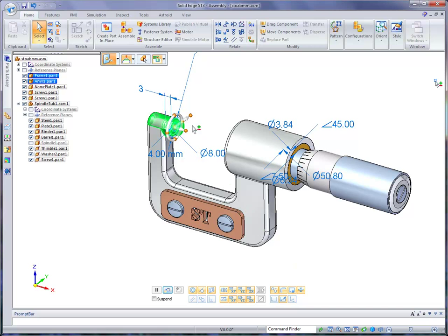What we want to do at this point is come up and identify just by clicking on the origin of the steering wheel. Just click it once and let go, and the steering wheel will hang with the cursor. And I'm just going to move it up out of the way so that we can kind of see what's going on. I'm then going to change my primary location axis to go to the 12 o'clock button up here, or knob. Click on that, and it's going to move the primary to go straight up.